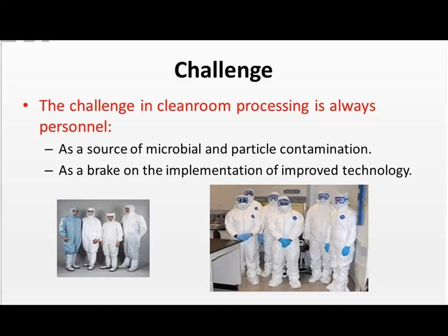As you can see on the left, that's the type of gowning that we might use where skin is showing in a non-sterile environment, but we are still gowned. We want to keep as many particles as possible inside those coveralls, not sloughing them off into the environment, and also protect the product from skin contact, because there is bioburden on our skin. So we need to make sure that we have solid training and gowning procedures for either type of manufacturing, and that we're monitoring our personnel. And this is the point of our environmental monitoring.